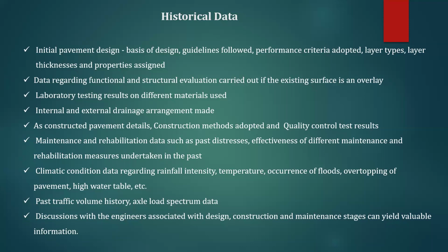So temperature, even the temperature. Suppose, let us say, if we take Rajasthan, temperature is very high there, 45, 50, 55 degrees. So your bituminous concrete pavement top layer, because of that temperature, will definitely lose the strength of its resilient modulus or elastic modulus. Sometimes you're using poor mixes, and a lot of rutting will be there. When I was working in Kishangarh, Udaipur, Ahmedabad of Rajasthan, I have seen a lot of rutting in the wheel path direction. You know what is meant by rutting, okay? It is something like a 20 mm vertical depression along the wheel path direction. So several things we have to understand.